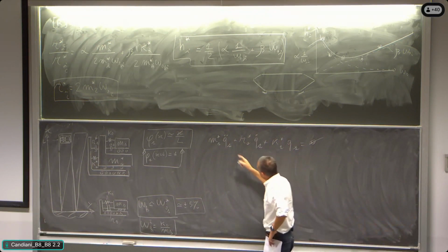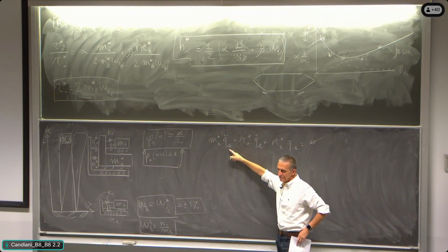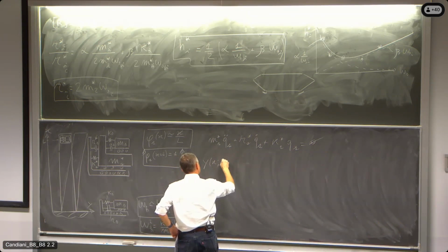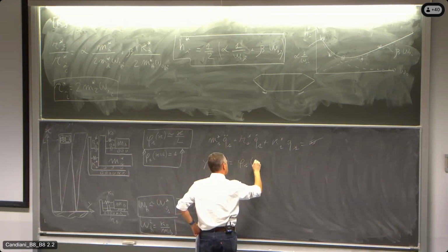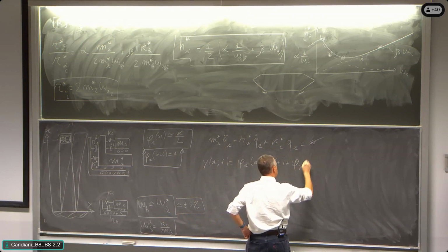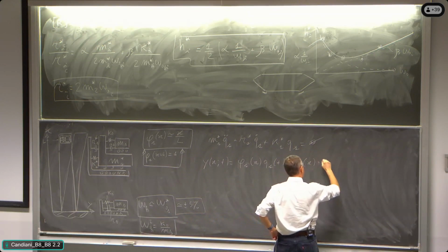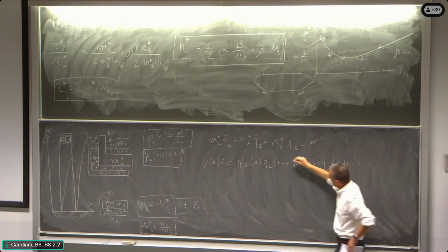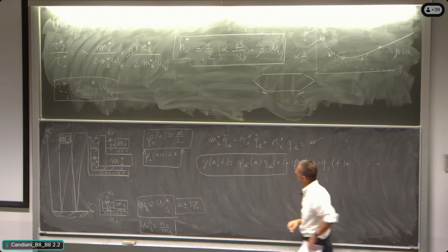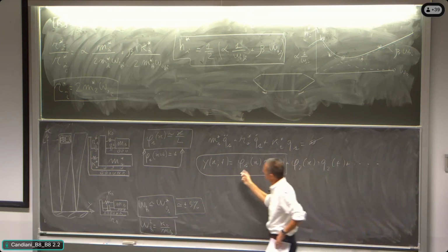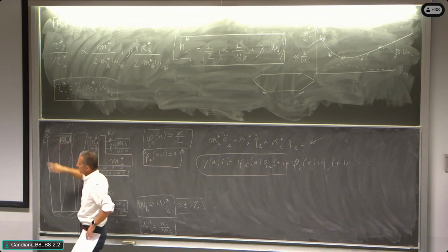Well, what is the meaning of the principal coordinate Q1? So we write y of x and t equal to phi 1 of x times Q1, plus phi 2 as a function of x multiplying Q2, plus and whatever. But we are focused here. Who is Q1, when we are normalizing the mode shape to 1?